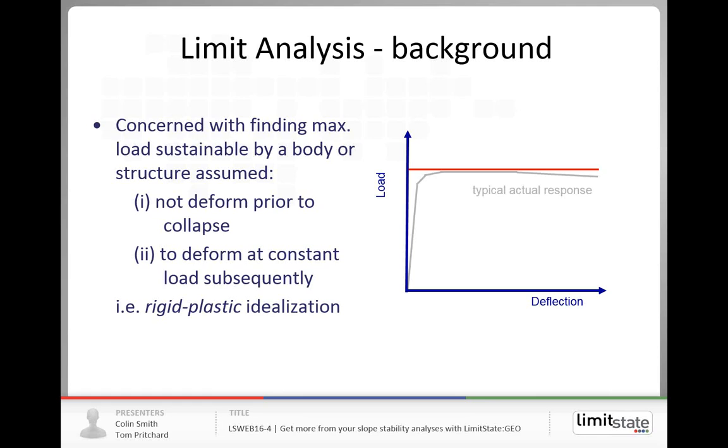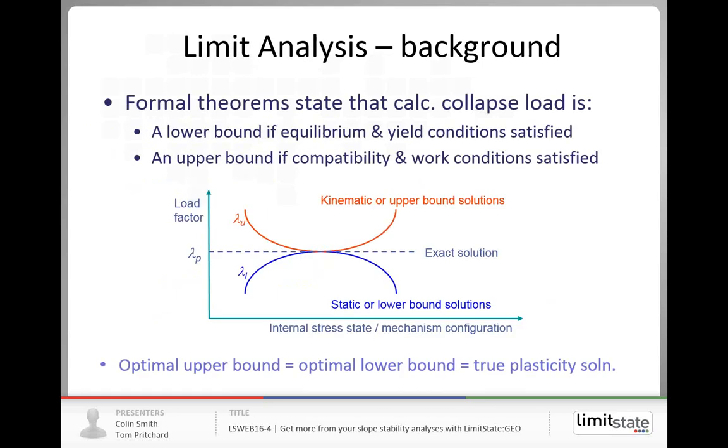Now, all these methods are based on limit analysis. This is a form of analysis that assumes a rigid plastic behavior of a material. So it's an idealization, but it's commonly used, and has been used for decades in geotechnics. And the very nice thing about it is that you get what are called the upper and lower bound theorems that allow you to determine the true plastic collapse load. So these are rigorous plasticity solutions. If you adopt what's called a limit equilibrium approach, then some of these conditions are relaxed somewhat.